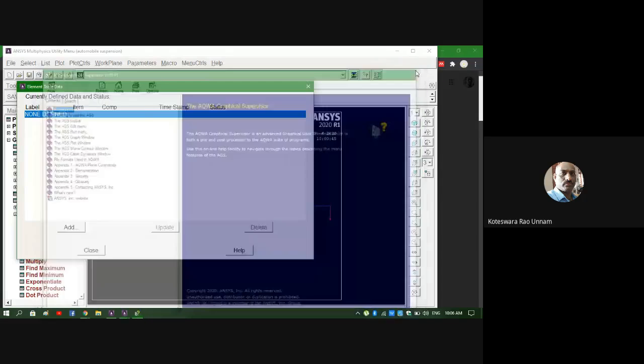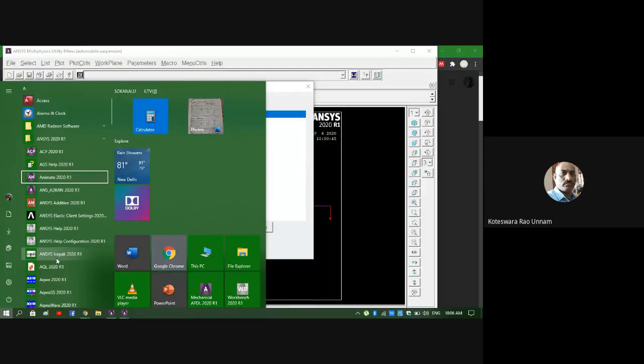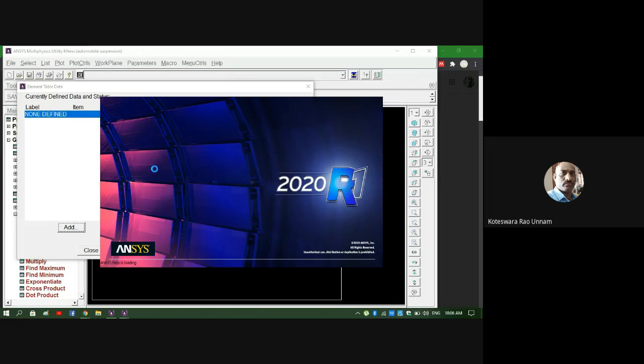If you go through the help document, like what I already told in the earlier case also, then you can open the help document and you can see what are the sequence numbers you require for defining shear forces and bending moments. I know them, but still I'll show you how you can get it. If you don't know that, or if you forget those values, this is how you can check those things from the element documentation. Let us wait, it is taking some time to open.